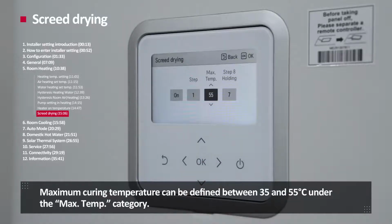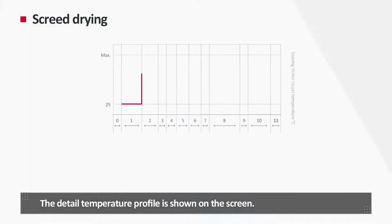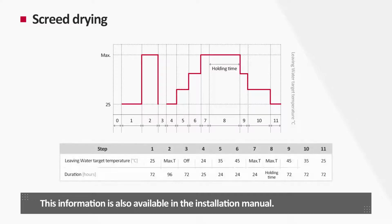Maximum curing temperature can be defined between 35 and 55 degrees Celsius under the max temp category. Lastly, choose how long you want to hold step 8 stage. You may hold this stage from anywhere between 1 and 30 days. The detailed temperature profile is shown on the screen. This information is also available in the installation manual.